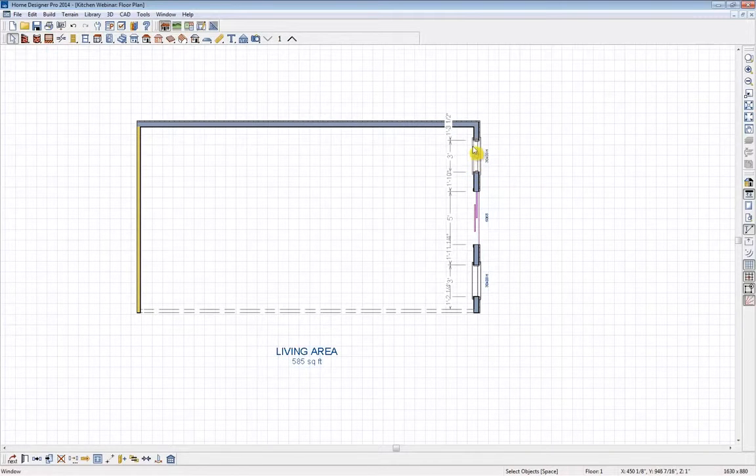I'm going to single click on the interior of the window to get our interior dimension here. Single click on the dimension line, and let's change that to 17 inches. And do the same on this side. Select the window, select that temporary dimension, and there we go. Now we have our accuracy for the openings.